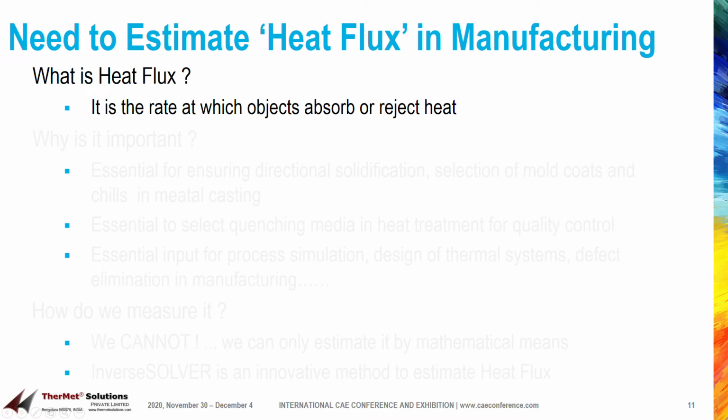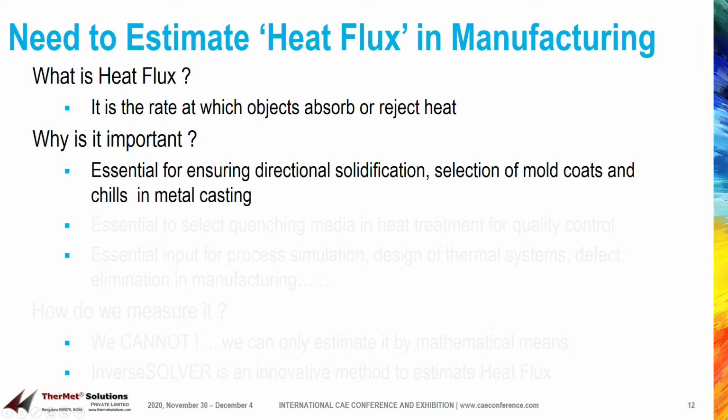One of the biggest problems in thermal process simulation and control is the estimation of heat flux, the rate at which heat energy is transferred from one system to the other, from one component to the other. There is hardly any manufacturing method where heat transfer does not play a crucial role. Take metal casting. An estimate of heat flux is essential for ensuring directional solidification. Selection of mold coats, chills in metal casting, etc. are governed by the heat transferred from the liquid metal to the mold.